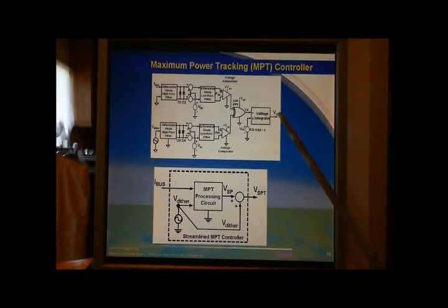Consequently, at this point, the output of the maximum power tracker, which is VSP, goes into a steady value, stopping increasing or decreasing, and becomes the final value corresponding to the peak power voltage.